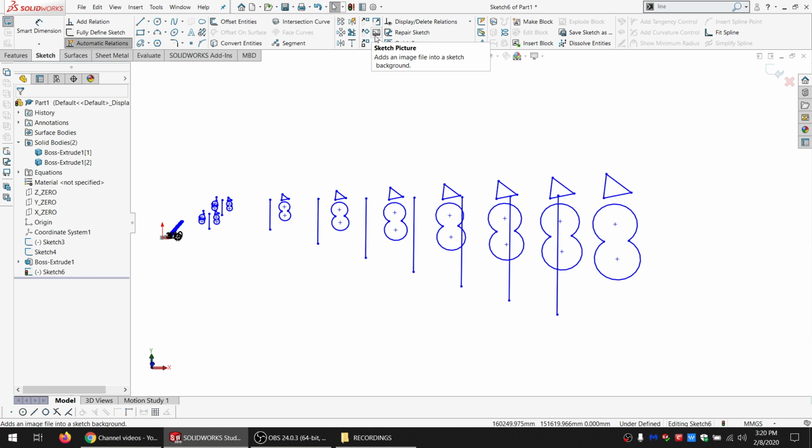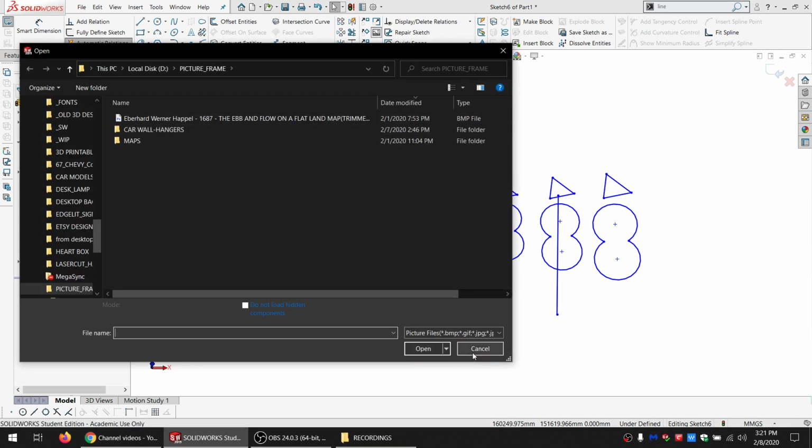The other thing that you can do with Sketch Picture is sometimes you want to put a decal on something. And SolidWorks does have a decal feature, but it's temperamental and it doesn't work for all circumstances. So you can actually just use a sketch to hold a sketch picture, and kind of make a decal. It's not really a great design thing, but if you're just trying to make your final design look nice, or do kind of a render type deal, it can be useful. But there are options in there, but I'm not even gonna bother with it.